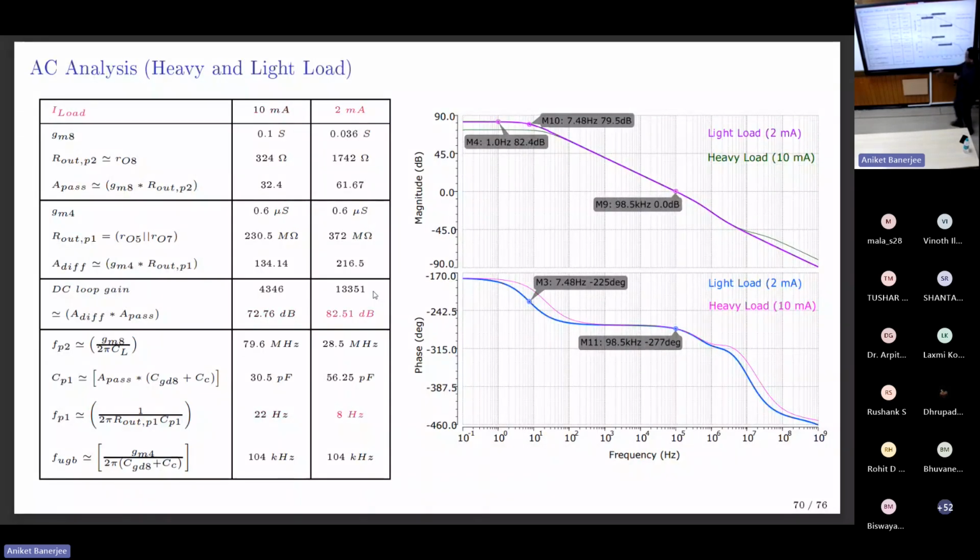Is to achieve this and this together. So this is the breaking point. When you say low IQ, if you want to make this 200 kilohertz or even 400 kilohertz or megahertz, that is the point I would want to go to high IQ or folded cascode. It means achieving this 4000 gain, compared with the previous design, which was 50 microampere current, 1000 gain. This is a 120 nanoampere design with 4000 gain. So there is a trade-off.